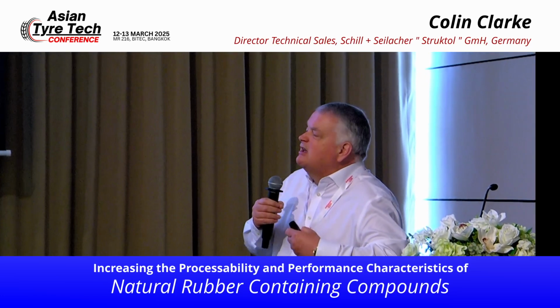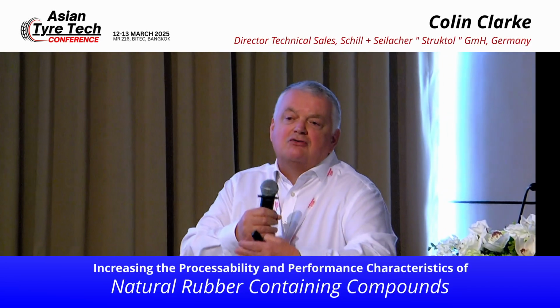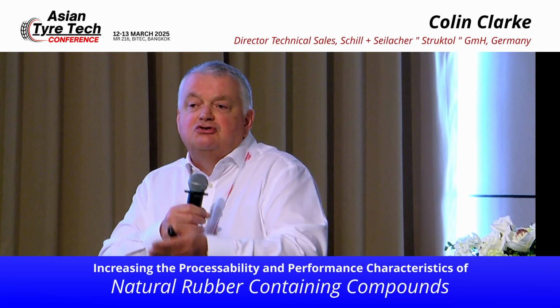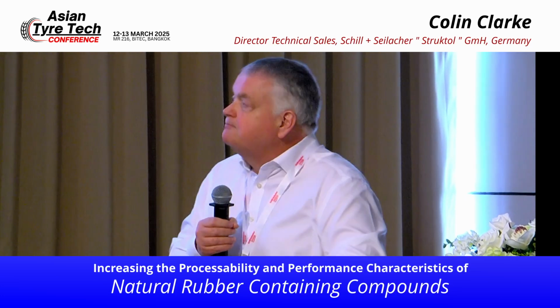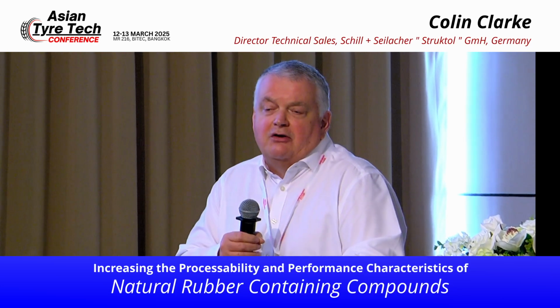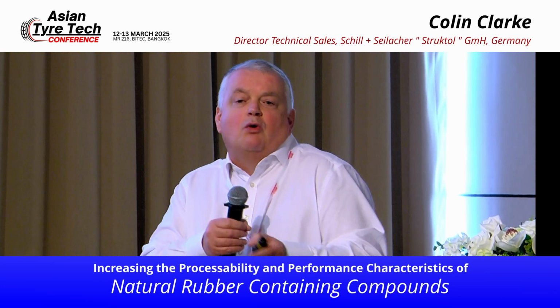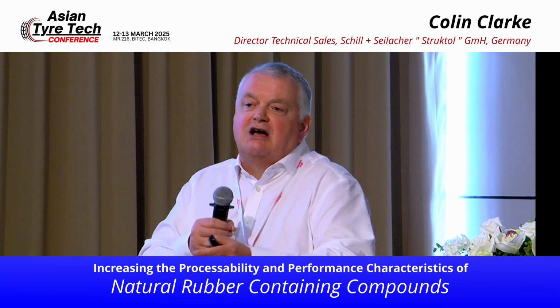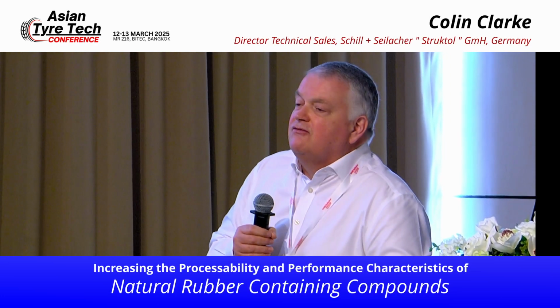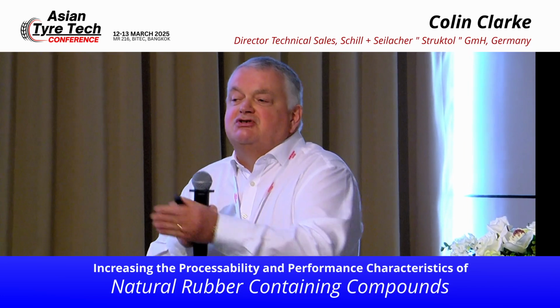This is relatively inefficient, long-term processing, and in a way, multiple mixing stages will tend to degrade our natural rubber properties. Our target, therefore, is to combine the peptizing, the filler addition and the polymer blending into one stage. So can we bring these 2 stages together? Can we eliminate a mixing stage? Can we save all of that energy and put it into one mixing stage?